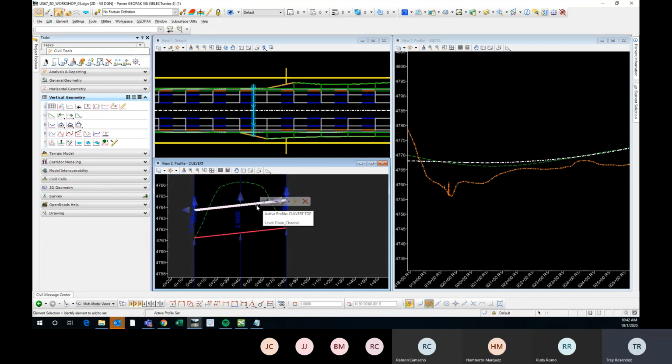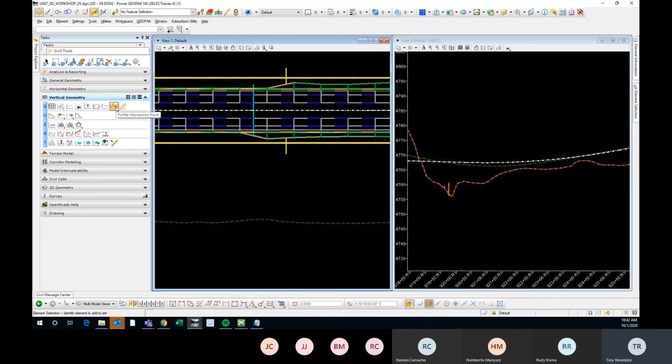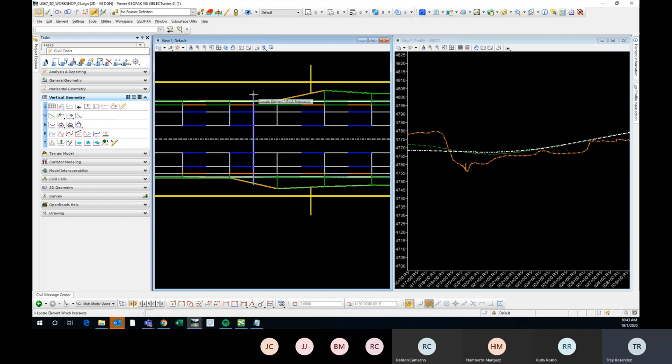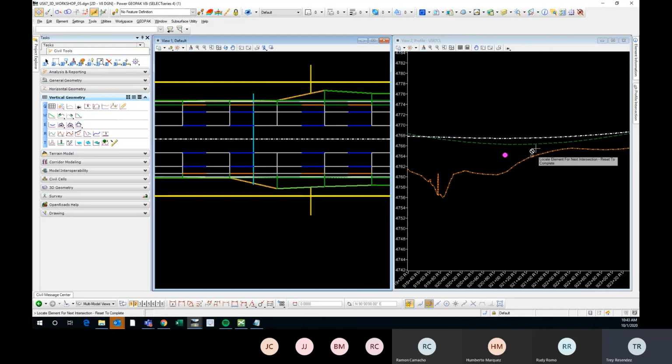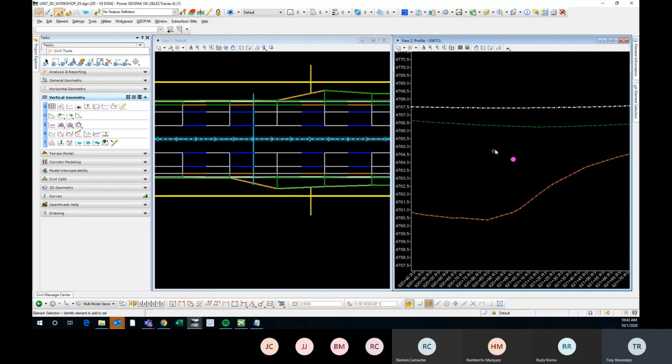So now when I use the profile intersection point command, let's see what happens, and we'll talk about it. So profile intersection, so locate element to show intersection. In this case it's going to be our alignment, and then locate element which intersects. It's going to be the culvert. So see, now we can see that this is the top of our culvert.